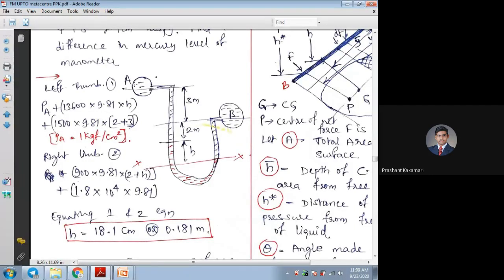All are towards PA in this type of manometer, which is the normal type. So wherever it is high pressure, you can start from that end so that convenience will be more here. So PB side pressure is more, so we'll add the lowering side pressure. On the left side, the pressures are rising, so liquid columns are rising here. What they are doing, rho GH of mercury, rho GH of liquid on the A side, they are rising towards A. So here we are adding earlier. So similar case in the inverted tube, it will be opposite.